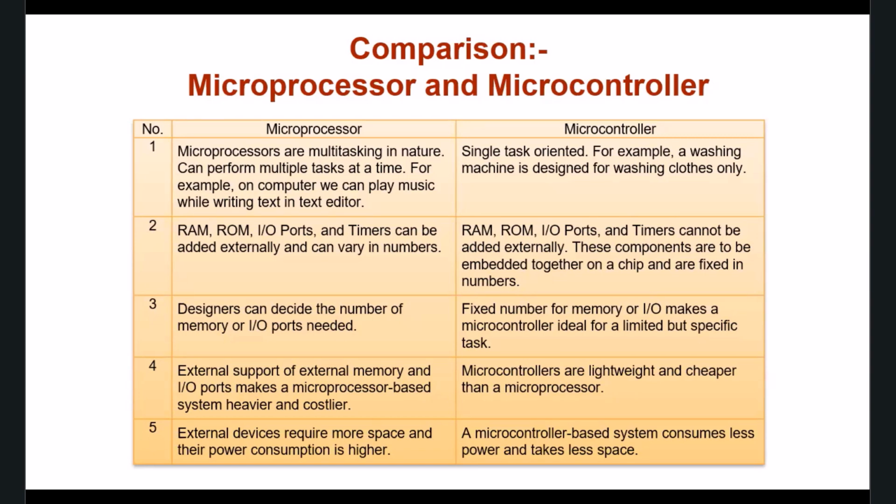That is the difference. Now, designers can decide the number of memory and input-output ports needed to develop a system using the microprocessor. But in case of the microcontroller, a fixed number of memory or input-output makes a microcontroller ideal for a limited but specific task.